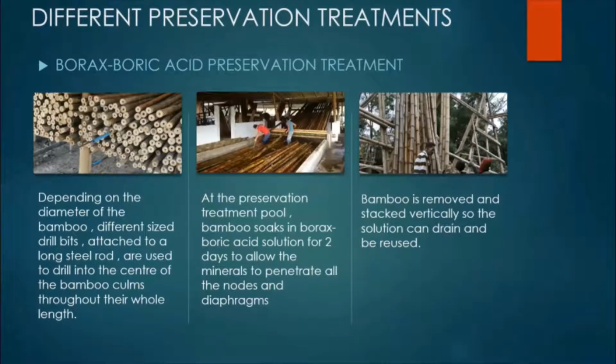For example, the smaller bamboo species like Paisri suk can be stripped for weaving mats used as a substructure of our bamboo roof. The thicker, more mature bamboo species, Python and Pyhawk, are used for structural columns and beams. Borax boric acid preservation treatment. Borax or sodium borate is a soft, colorless, powdery mineral that dissolves easily in water. It is a natural insect repellent and preservative.